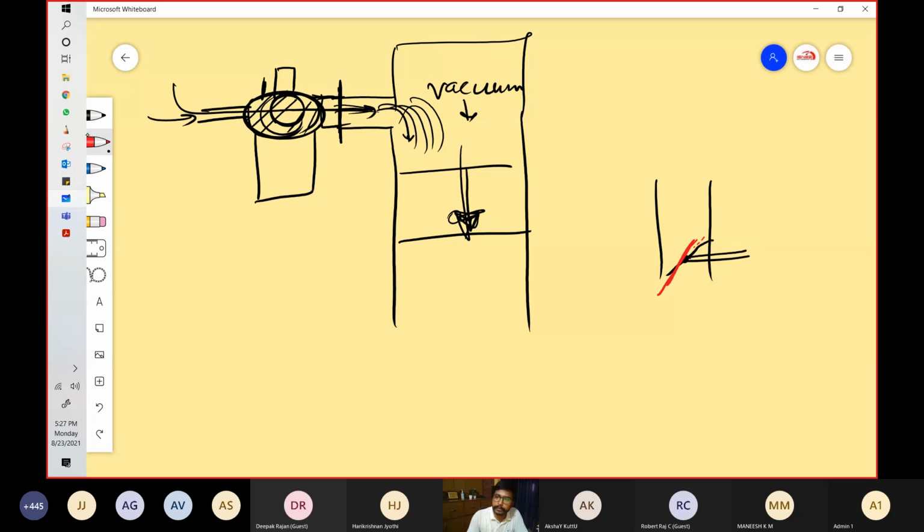So this area increases, and then there will be a time when this position will be like this, like the flow can happen in this way, and then there will be a time when this is almost closed. Not closed, almost closed, but there is a small passage left here. So when you pull up the choke, you let more rich air fuel mixture come inside the combustion chamber, and this is how it works.